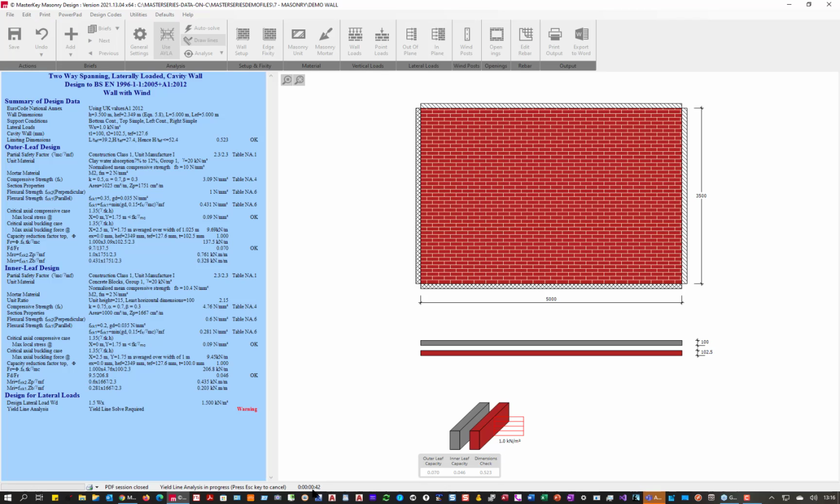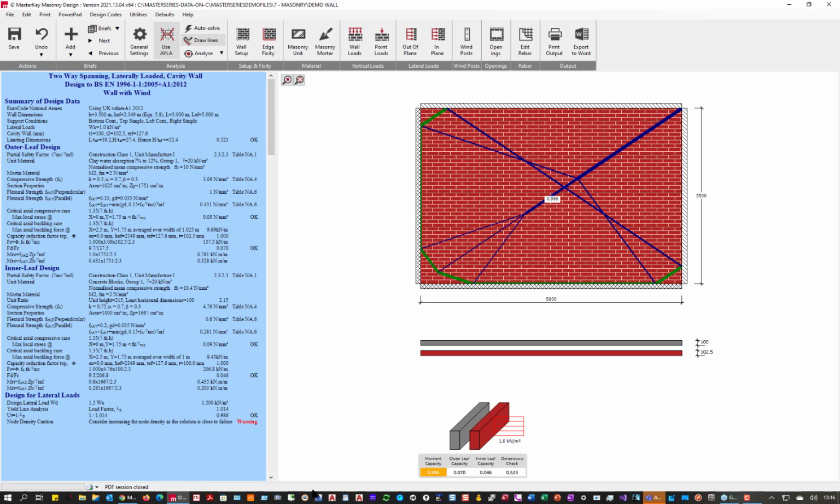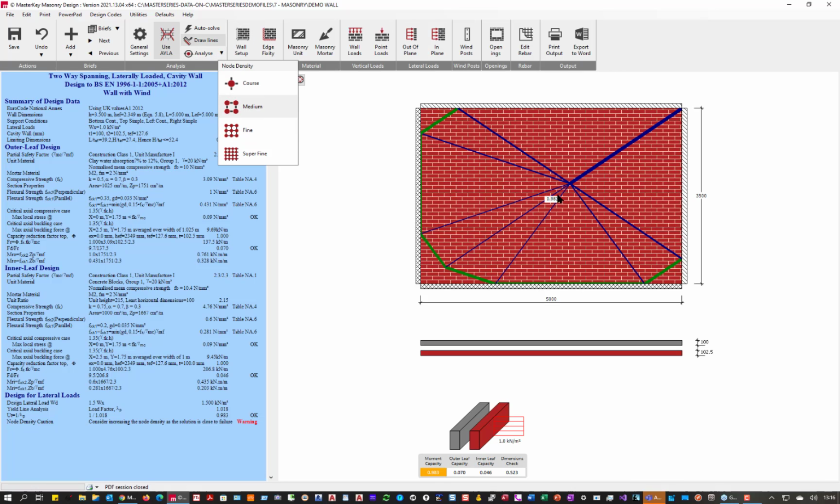And we should be nearly there at 45 seconds. So normally I don't recommend people go for fine or even super fine until we get there. And you'll see between medium and fine there was nothing, no change. 986, I believe it was 986. Now the beauty is that it'll remember the previous 983, so it's moved by 0.3%. So I'd be happy at that. That's fine. That's going to work. So I'm good for that.